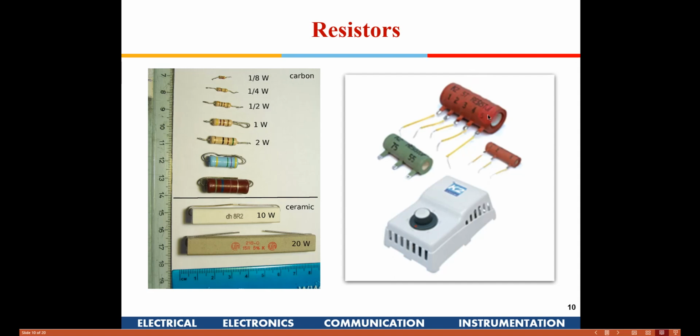This was a very inefficient way of doing it. Nowadays we have electronic regulators. In olden days resistors were connected in series to drop the voltage, whereas I squared R heat used to be generated in these, so that is why these were so big in size.